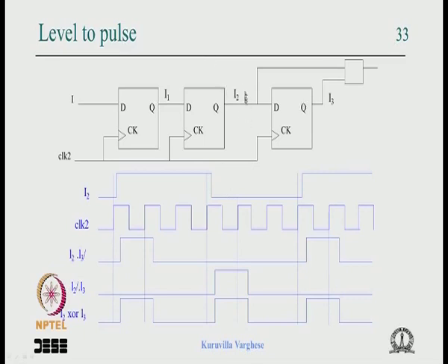Okay. Here for analysis that is enough, we do not have to analyze I. The clock comes, and when the I2 comes, you see the clock comes, so the I3 will go high in the next clock edge. But you see, we are looking for a scenario where I3 is low and I2 is high.